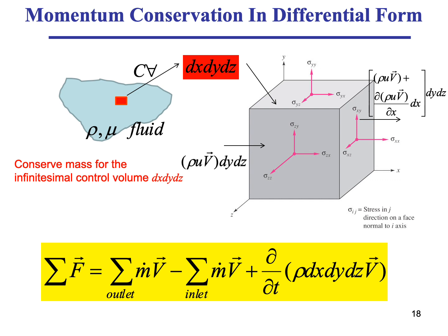But now let's look at the momentum fluxes. The momentum flux that comes through face x is the mass flow, so it's the area dy dz multiplied by the m dot, rho u dy dz is my m dot, and then I have the v, so m dot times v. I've done that at the inlet, and what leaves is my function rho uv. Let me take it as just a function, or you can substitute capital V with just U, because we're looking at the momentum in the x direction. So we come in with a momentum rho uv times the area, and we leave with a new level of momentum rho uv plus this extra bit of change in momentum times dy dz.